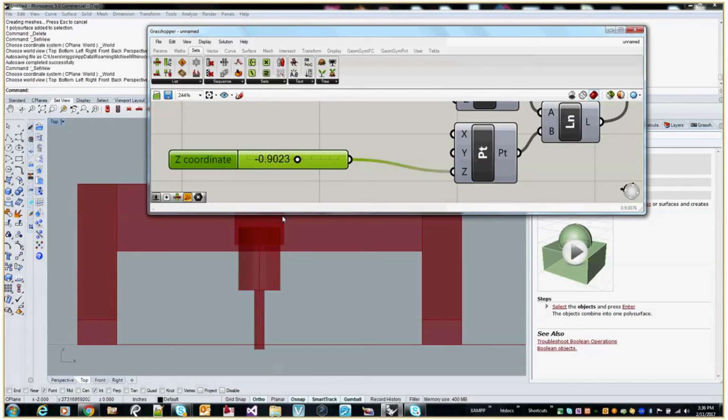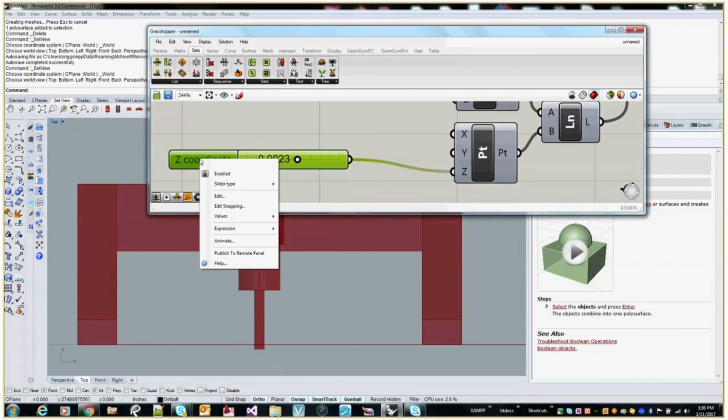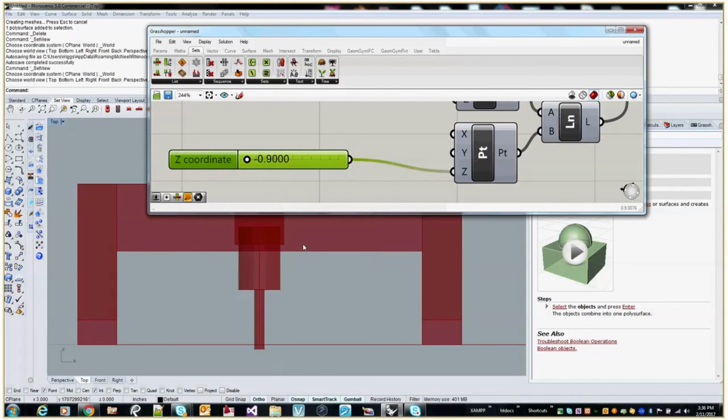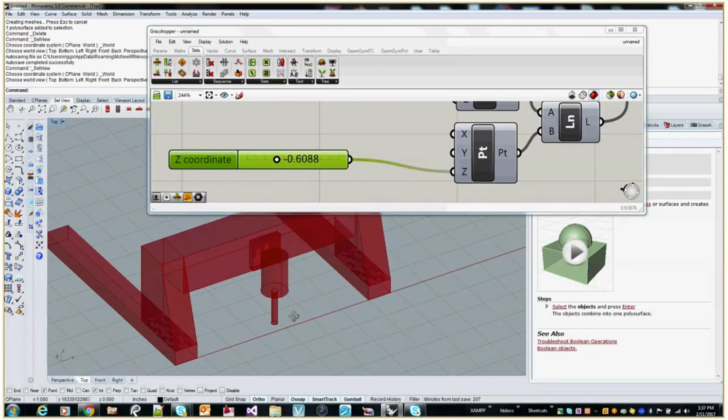So I'm going to say it's -0.9. Set the value. We want to set our minimum. -0.9. Accept that. Commit the changes. Now, I'm not going to go beyond those limits. I might need to home to something like that if I have like a top of spoil board or something like that, or top of material, depending on your approaches to milling. But yeah, that's basically how we set those. Now we can control this whole machine, and it's good to go.